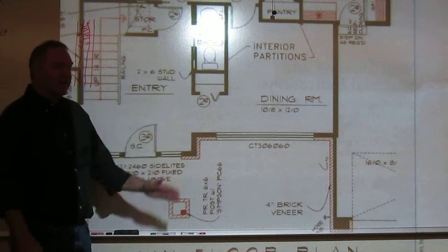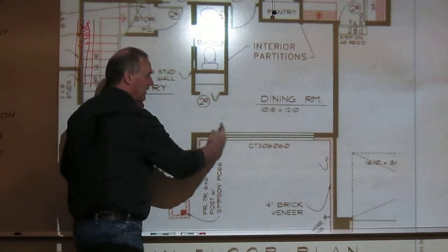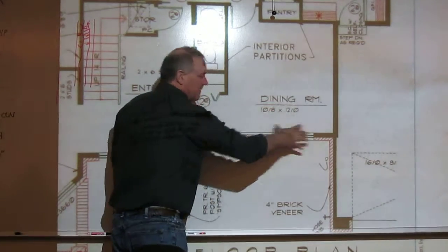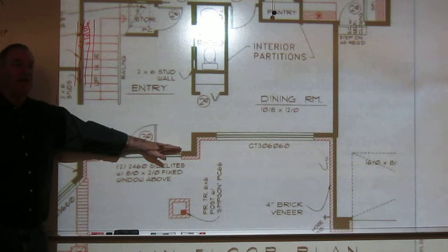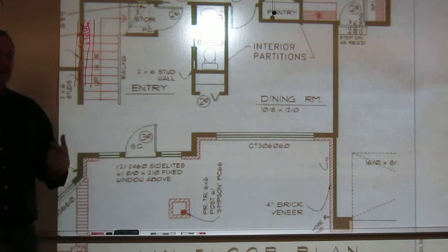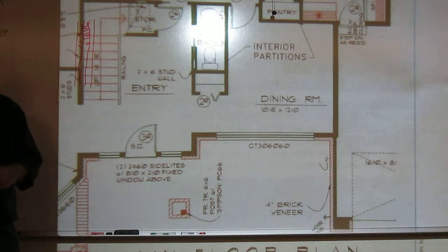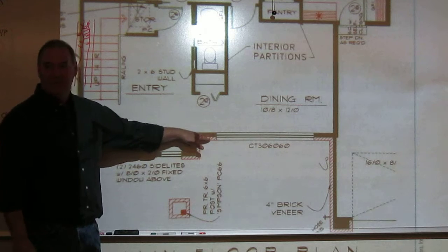Now we're making this section 4 feet off the floor, so we're cutting through a piece of wood here, piece of wood here, piece of wood here. Is it really solid at 4 feet above? No, it's not. But we represent it as a solid piece. So don't draw the individual studs. Just a couple of lines. We probably won't hatch them. Not many people hatch in the residential market.